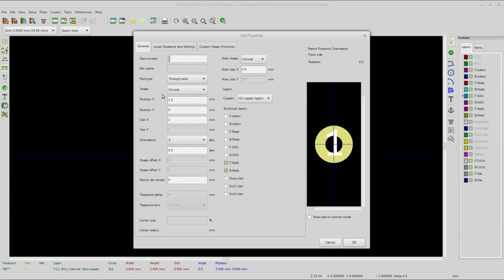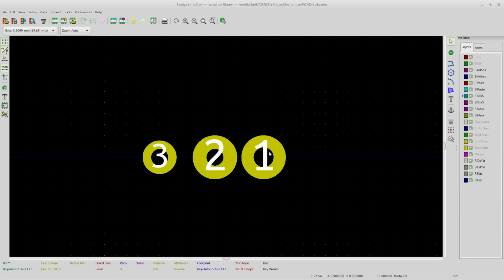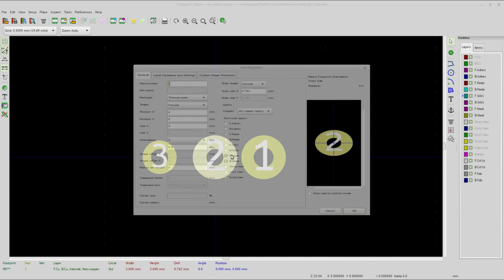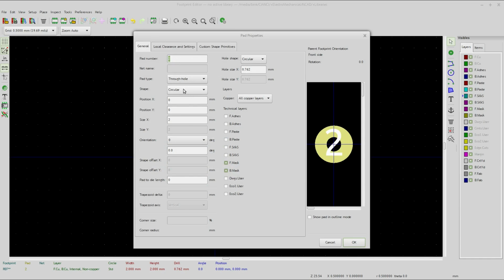And so to be on the safe side, you work it out how you want to work it out, because maybe you don't like having too thin of an amount of copper there. And also the thinner the copper, maybe the easier it might be to rip off. But remember, this is through hole, so it's going through the other side. So it's got a pretty good anchor there.